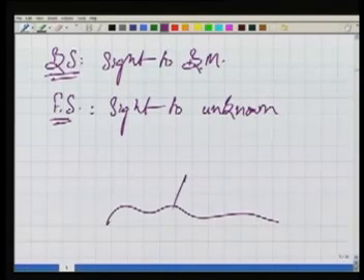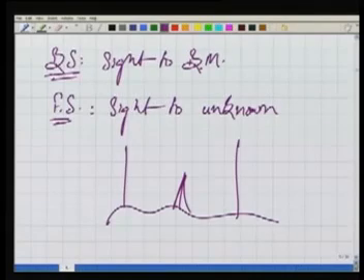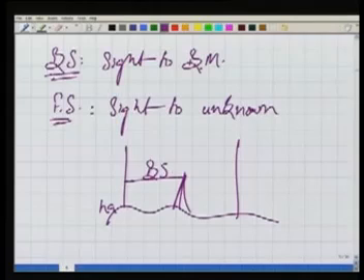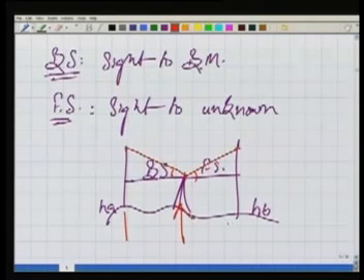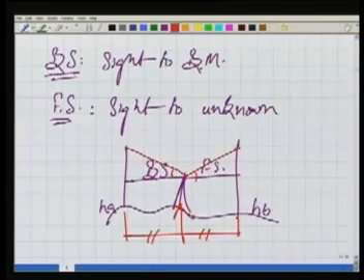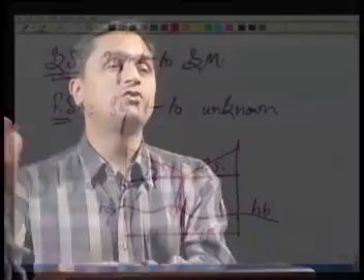So in this case, if I know HA, this is my backsight, and we want to determine HB, this is my foresight. So what we saw here, we can eliminate the effect of non-parallelism error by keeping my level somewhere in between so that these two distances are equal. So the effect of this error will be gone. And this is what we say balancing backsight and foresight.